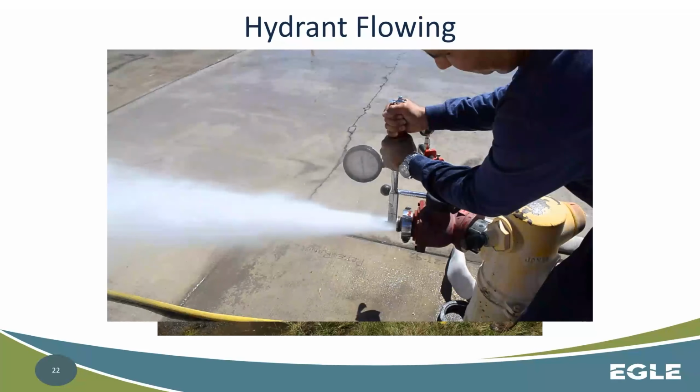And it also helps tell us when we're starting to lose flow over time that we're having issues with the water mains associated, right? Or valving or something else, right? If we can't get a flow that we anticipate to come out of a hydrant that we know we've achieved previously, then there's something going on larger.